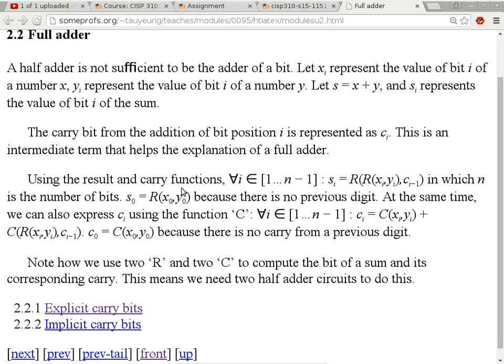It will be 64 times the amount of time to finish one bit adder, right? Because each one depends on the availability or the validity of the carry bit from the previous one. Now every logic gate is implemented by transistors, right? You still remember the transistor picture?